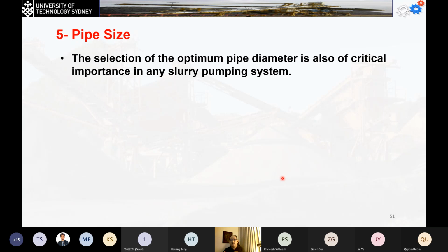Mainly because the mass flow is a relationship between the velocity multiplied by the area. The smaller pipe has a throttling effect, and thus we get higher velocity, but the area is small, so we get less flow rate.